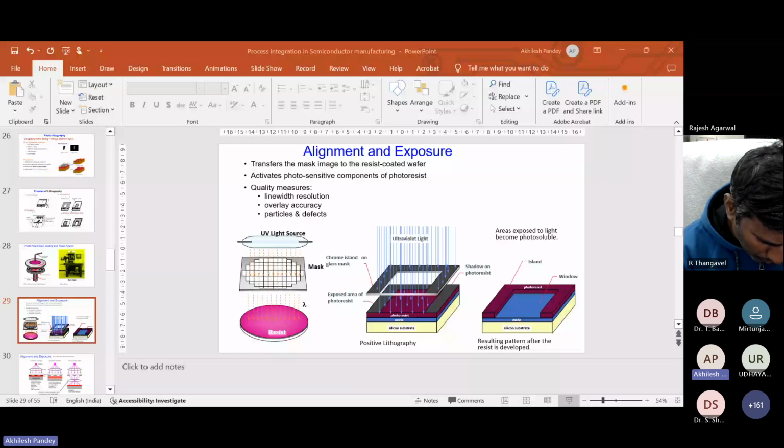The main applications of this etching process are transferring the photoresist pattern onto the wafer substrate, preparation of a smooth damage-free surface for epitaxial growth, producing clean residual-free surfaces for subsequent device fabrication, studying the defect structure of the semiconductor, and forming the mesa structure.